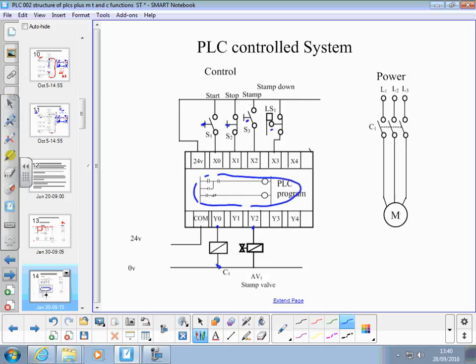Yeah, from your question earlier. So this is telling the PLC what state the equipment's in, and this is controlling the state of that piece of kit. The rest of the interaction, when them relays come on and go off, is dealt with by your program. Notice that this bit is exactly the same as it was before. It'd be the same contactor and the same valve.